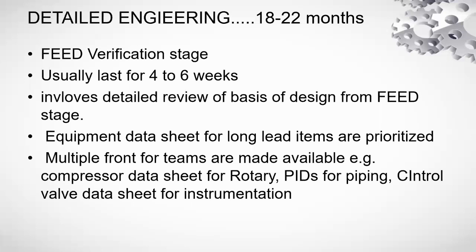This particular point is called a tie-in point, and it happens that no concrete information was available or the basis for this was not finalized. Now, this in a way affects the selection of the compressor in the facility, because there is no surety on what pressure is required at the outlet of the compressor. So these kinds of open points, detail engineering contractors are expected to find out during this FEED stage.